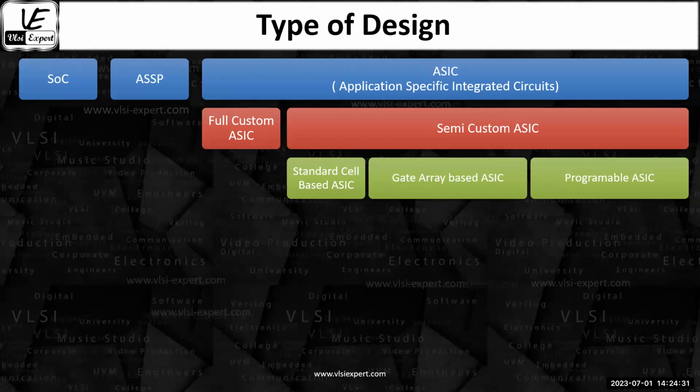And then you will say, okay, how is that logic gate going to fulfill my requirement? Then I will say, okay, no problem. I have 10 different versions of logic gates. So for the inverter, there are 10 different versions of inverters. NAND gate, 10 different versions of a NAND gate. Now, what is the difference in those versions in terms of the specifications? Maybe one is going to drive 2 gates, another is going to drive 4 gates. From the voltage point of view also, maybe one is at a different voltage level, another at another voltage level, in terms of the threshold voltage, in terms of the power, in terms of the delay.